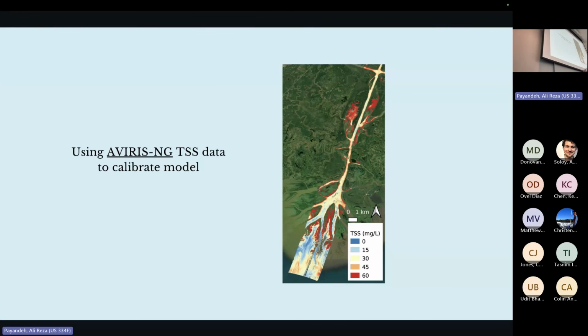These are sediment concentrations. We have so many acquisitions. You can run the model with different settling values. That's 0.3 that I told you. You can run it by 0.1, 0.2, 0.3, even smaller numbers. And then compare your results with these sediment concentrations and try to reduce your error.